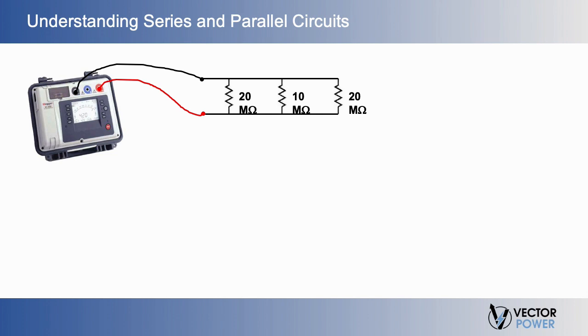When we add the insulation resistance values as reciprocals, we can see here that the total resistance of the assembled bus run equals 5 megohms. Now, measurements of bus duct or cable runs should also be corrected to a nominal length.